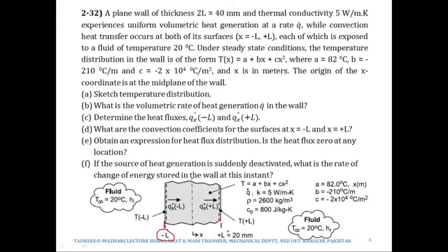So if you have a wall at your home, the inner face of the wall is inside the room, and the outer face of the wall is outside of the room. We are talking about the whole face. And so the outer face is at x is equal to plus L. So from minus L to plus L, the thickness of this wall would be 2L, which was given to us as 40 millimeters.